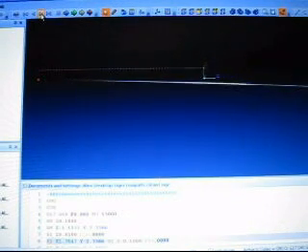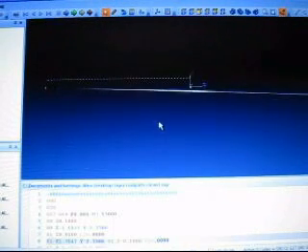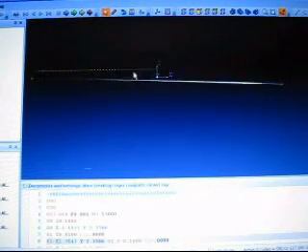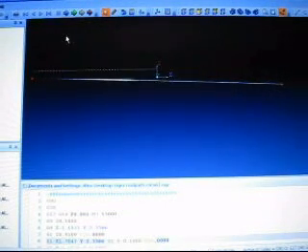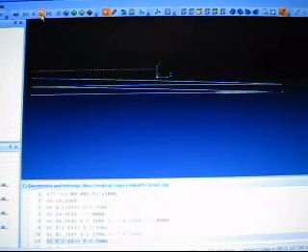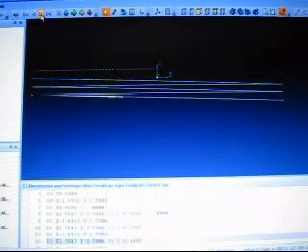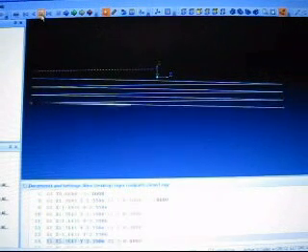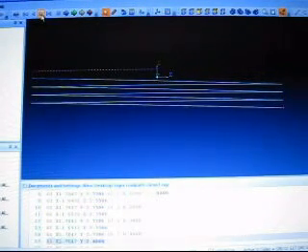And I guess you could use it on a plunge router. You know, you probably could plunge with it, but for the sake of saving, I got a 5-bit set for like $7 or whatever at Harbor Freight, so I'm going to ramp it into the material, be real gentle with it, take it real carefully with that thing.